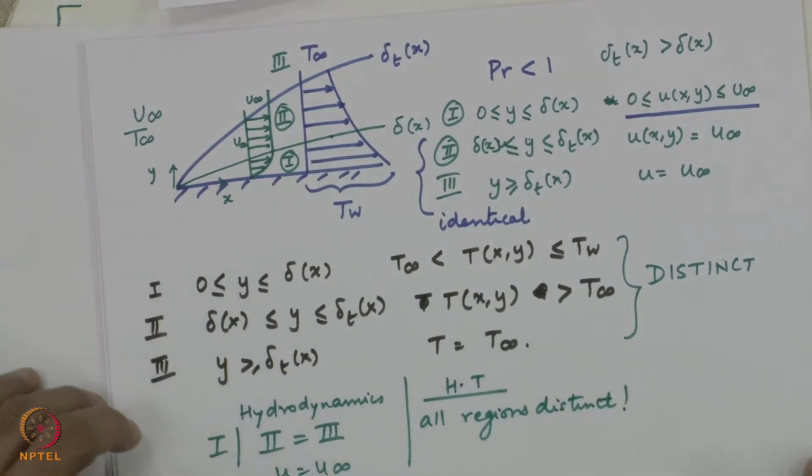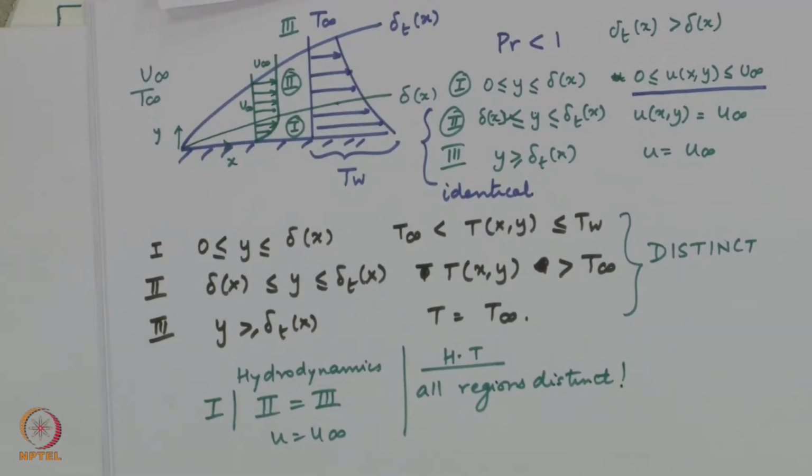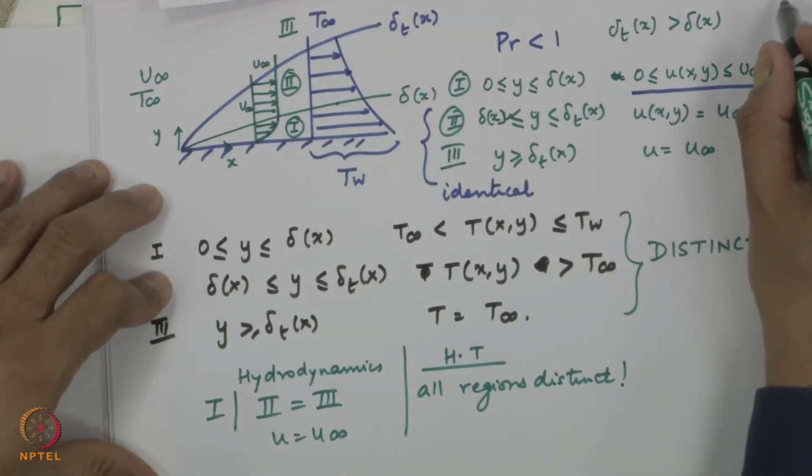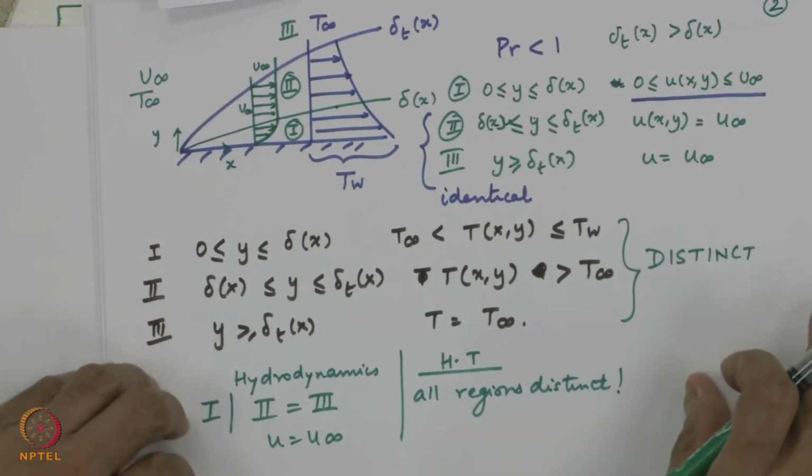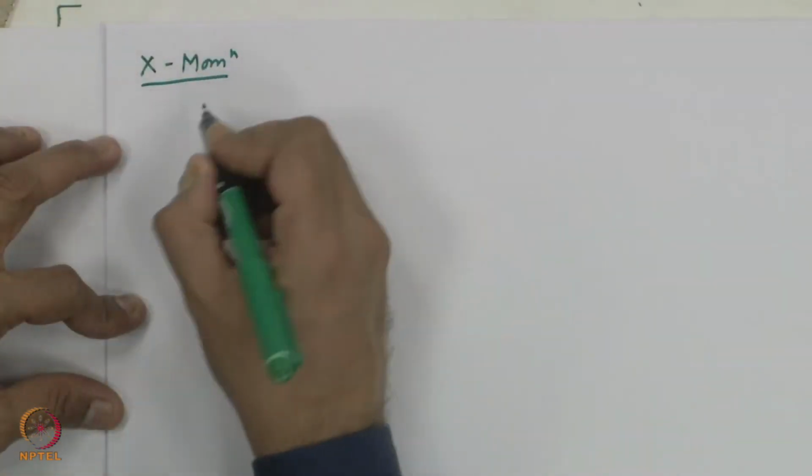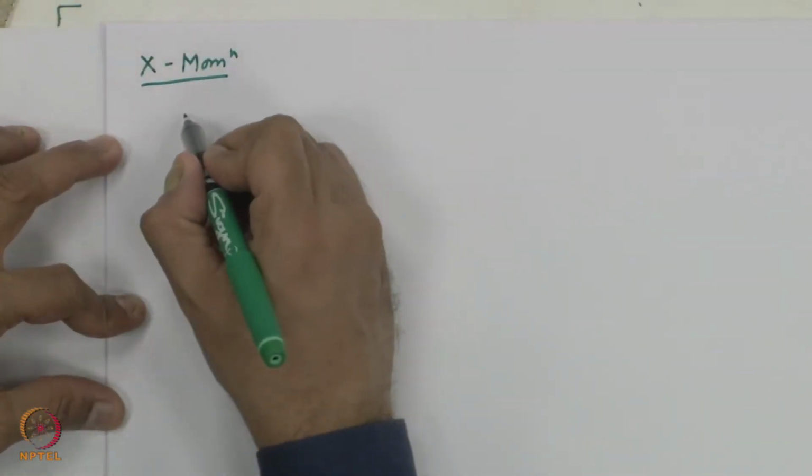Well, I have written all this. What does this mean? This is very important because it tells me what I need to do in solution of the governing equation. We have not derived the energy equation, but we all know what the fluid mechanics Navier-Stokes equation is going to be. Navier-Stokes equation is nothing but the law of conservation of momentum, Newton's second law, and I will write only the x momentum equation for you, and you will understand how things become simple.